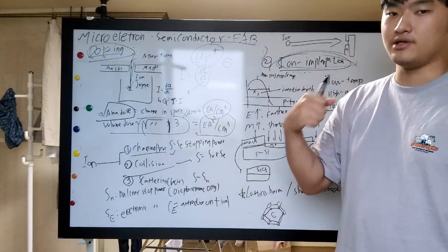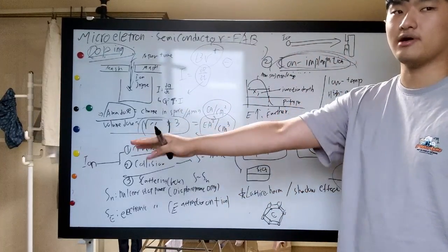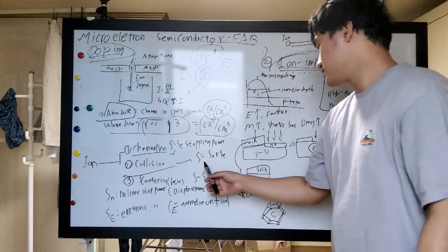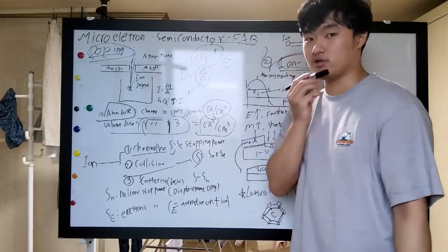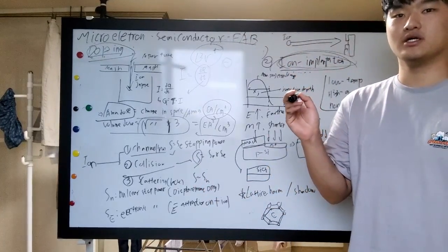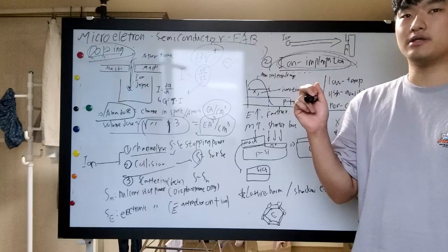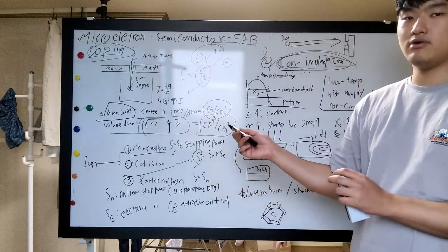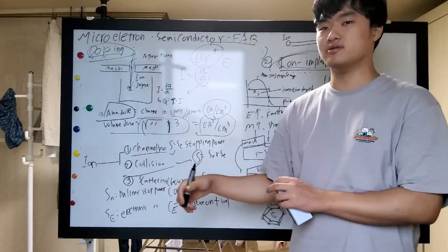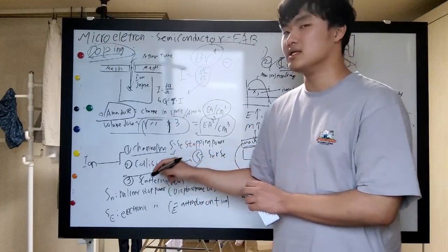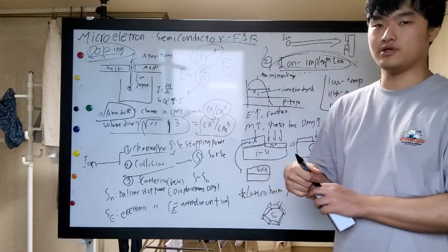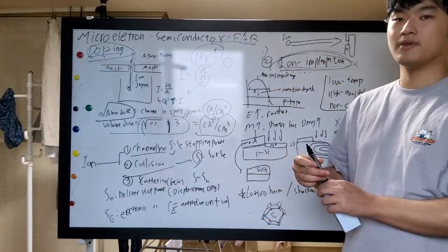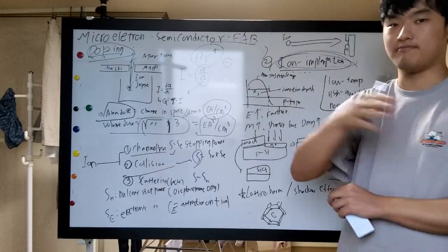Collision is related to both: the nuclear impact stopping power and the electron attracting stopping power, since the electrons are attracted to the positive ion. For channeling, since there is little or no impact with the nuclei, there is only the attraction of the electrons to the positive ion. And finally, back scattering is related only to the impact and being reflected.